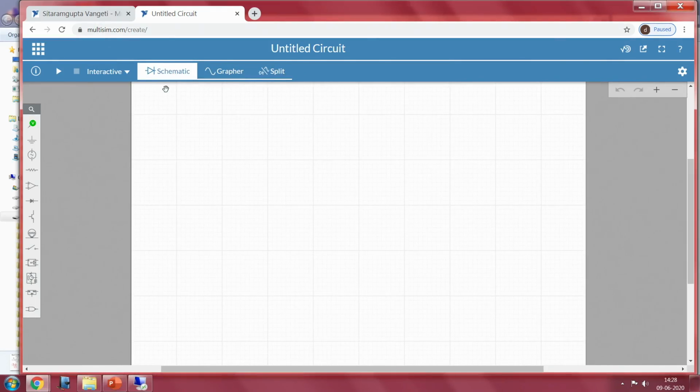In our practical applications, when we are designing filters or understanding the functionality, we may perform different simulations or different analyses on the circuit. Those analyses we can verify at this point. We have 4 different analyses available: interactive, transient, AC sweep, DC operating point. On the left hand side, it contains all the circuit components required to build it.